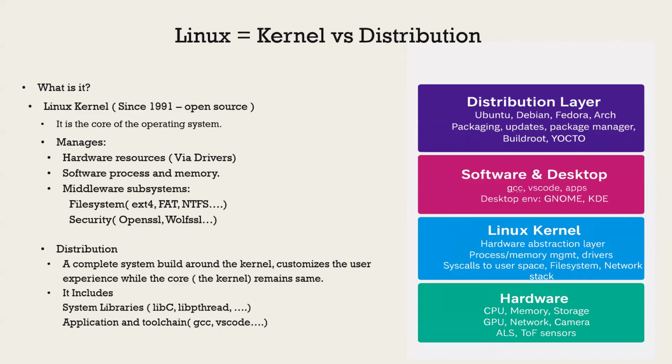So you are basically removing all the unnecessary core functionalities from the kernel. If required, suppose you have your own customized hardware, then you can add those in the Linux kernel in the form of a device driver. So when we set up a Linux device driver, those device drivers reside along with the Linux kernel.